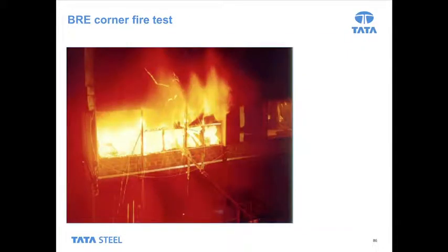The tests were severe. I don't know if you can remember that time temperature curve, but temperatures on that curve were probably about 700, 800 degrees. In this fire, the temperatures reached 1200 degrees. So this was a very, very serious fire. The temperatures experienced in this fire aren't typical of real fires, and they don't even reflect the time temperature curve that we use for elemental tests. Everything that we'd known at the time suggested that this building should have collapsed, but again, it didn't.